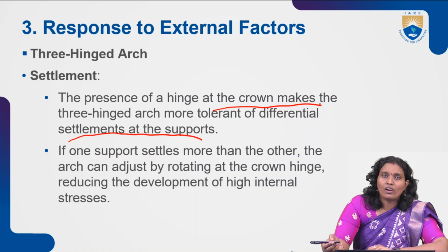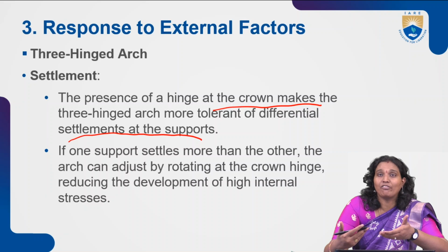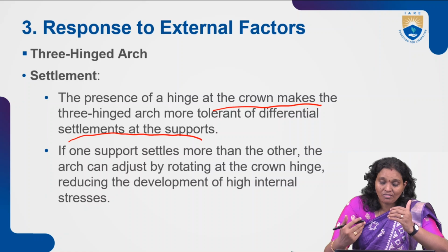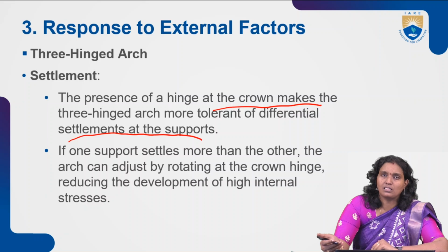This is one of the advantages, because we get fewer settlement problems, even though we may get more or unexpected deformations in these three-hinged arches. The presence of the hinged crown gives more tolerance of differential settlements at the support.